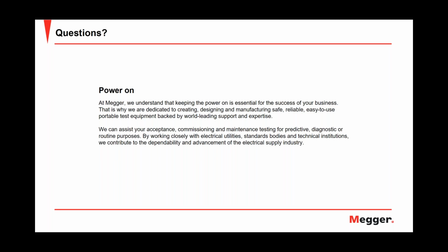Thank you. So, Robert, could you please kindly explain the physical phenomenon of the bang sound appearing when a certain level of voltage is applied in tests on faulted cables? Okay, so what is asked here is pretty much, why do you have the sound when you apply voltage to a faulted cable? It's pretty much the phenomenon of dielectric breakdown, like the flashover that you want to achieve, and what Javier explained very well, that you need that flashover to make the method work.